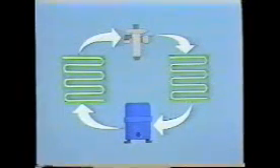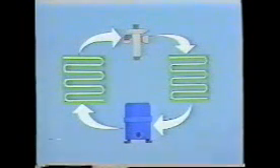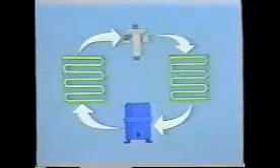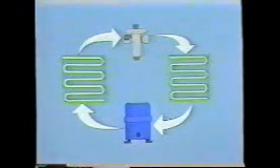You'll also see several condenser designs. In this program, we'll focus on water-cooled condensers. We'll see two common designs, a shell-and-tube condenser and a tube-in-tube condenser. Like evaporators, condensers are basically heat exchangers. They provide a place for heat transfer to occur so that the heat absorbed by the refrigerant in the system can be rejected again.